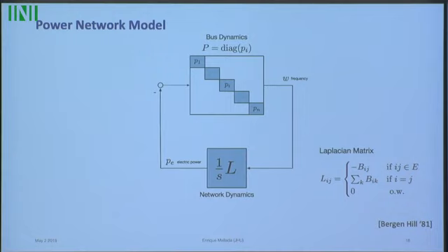So what is the model? It's the node dynamics, as was mentioned in the previous talk. I have individual buses here, the nodes of your network, and these are some dynamics that go from a certain power imbalance to frequency. And then we have the Laplacian, as in the previous talk, which is a sensitivity or linearization of the power flow equation. So I'm actually using a linearized version of the swing equations and a little bit more, and I'm going to say exactly what I'm going to do.